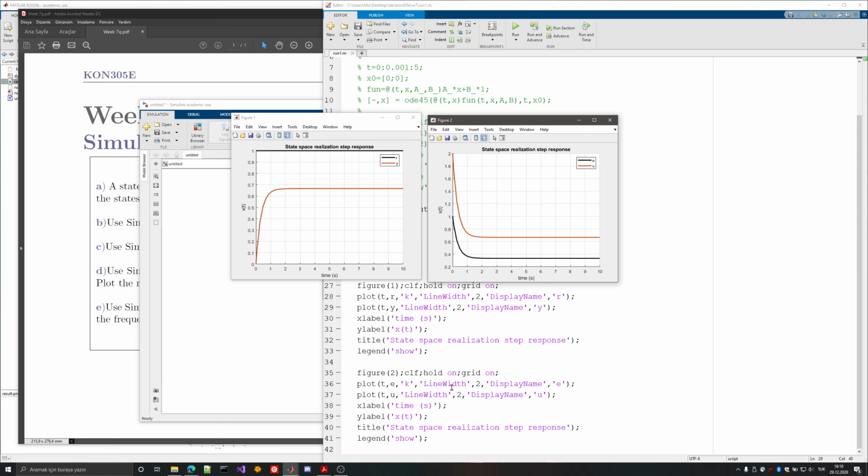So using this method by combining the coding and Simulink together, it's handy. You can just go ahead and make some changes in the visual side and just run the MATLAB code, and you don't have to repeat the whole simulation. So you can see now that my error and my control signal are basically proportional. They are related to each other.